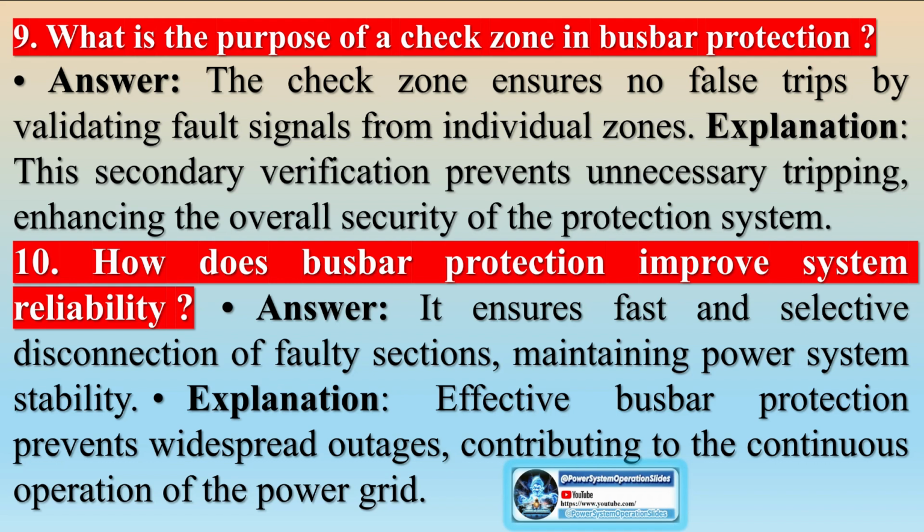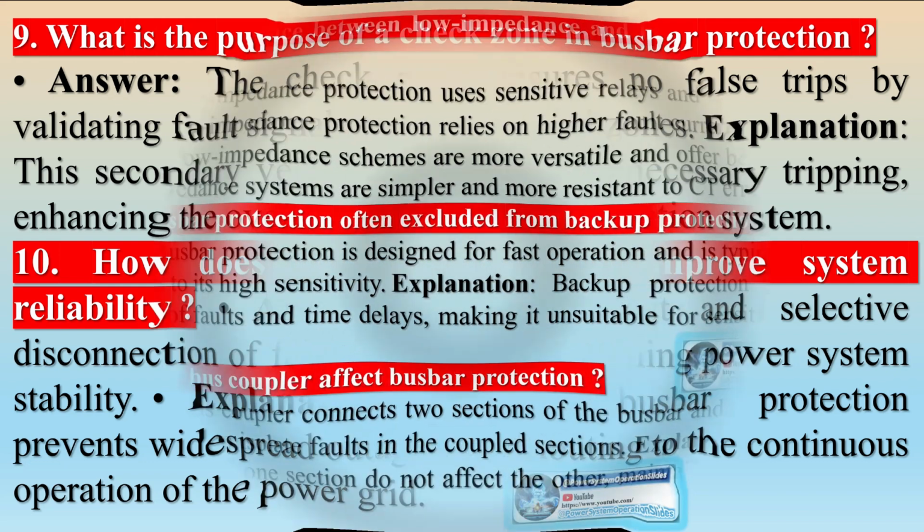Two contingency options allow busbar sections to remain in service. Second central unit: install a second central unit with associated fiber optic connections. If the first unit fails, the busbar protection can be manually switched to the second unit to maintain service. Adjust protection on feeders: modify the protection arrangement on in-feeding circuits to provide limited busbar protection.